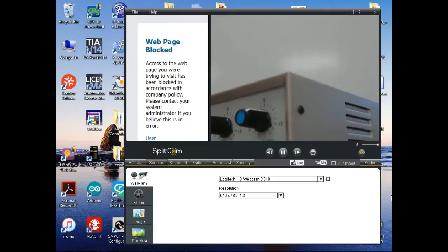But what you got to understand is that you buy timers that give you different time delays. So you could buy them in minutes, or if you needed 60 seconds, what could you do? You can double up, so you can take the output of this timer and do what? Feed it into another.